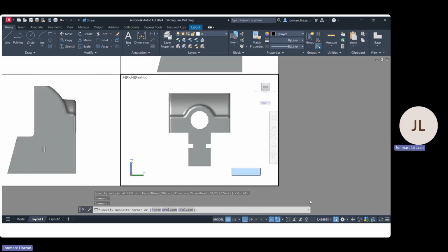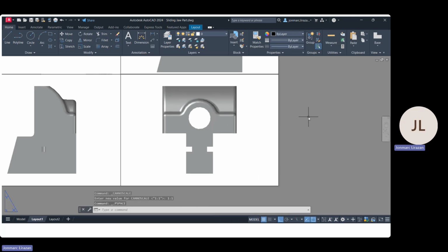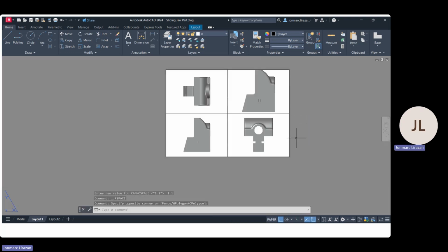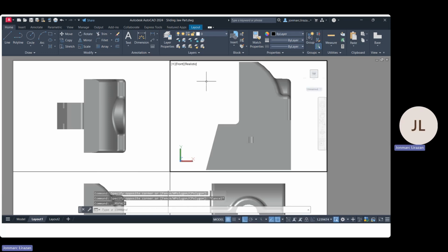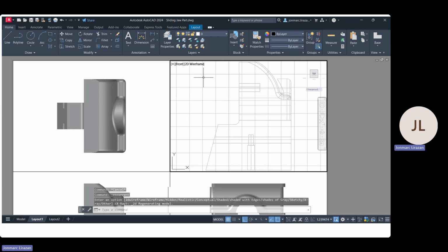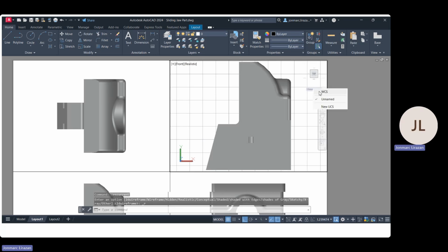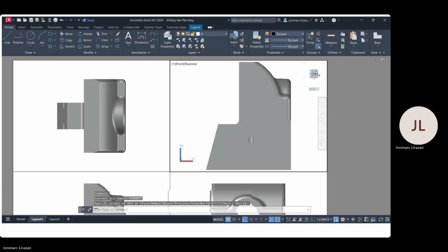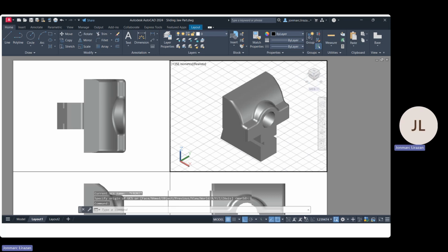Okay, again, since we are using 1:1 to the other drawing, so let's use 1:1. Okay, and you can edit this one. You can change this to X-ray, to the wireframe. Same for the others. Realistic, and this will be my isometric view here. Okay, then again 1:1,